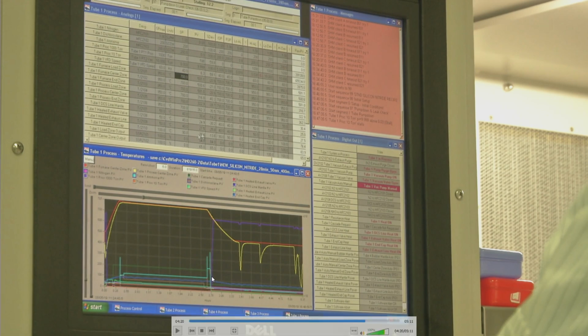nitride, right? Once the deposition is done, the feed gas is stopped, so both the gases are switched off, and then you cool it down. While you are cooling down, you will flow nitrogen gas to take out the residual precursor gases present in the chamber, in order to arrest any deposition that might happen during ramp down time, right?